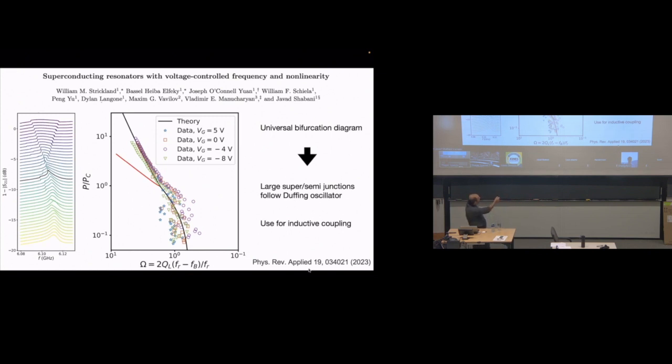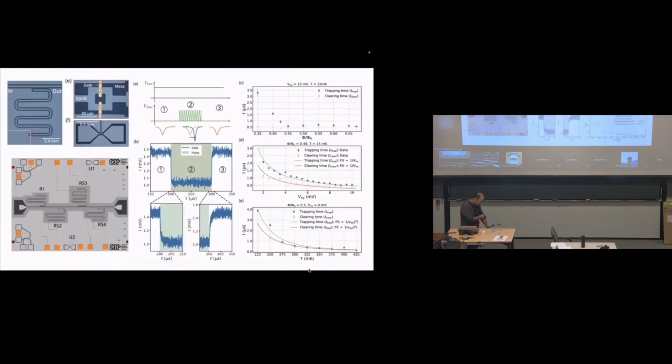But when I go to minus 8 volt, maybe my Andreev bound states are lossy. Maybe they are resistive. Maybe there's a problem, right? So it's especially important to know that when you are depleting these junctions, do I have resistive modes out there? And the answer is that pretty much we don't see anything over 2 decades of data. So as an element of the circuit, again, it works perfectly fine and is nice.